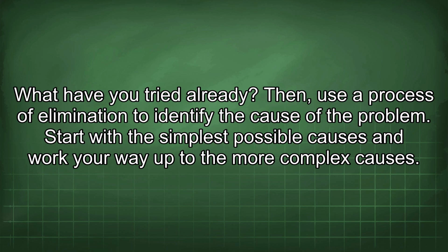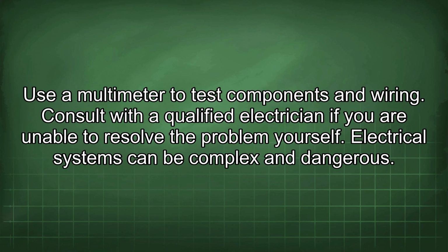Then, use a process of elimination to identify the cause of the problem. Start with the simplest possible causes and work your way up to the more complex causes. Use a multimeter to test components and wiring. Consult with a qualified electrician if you are unable to resolve the problem yourself.